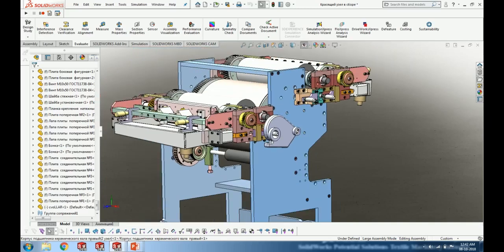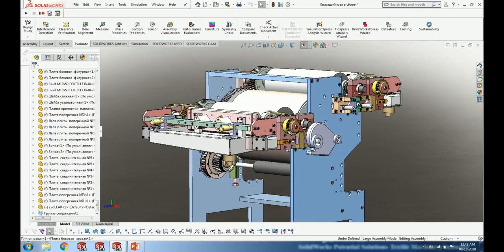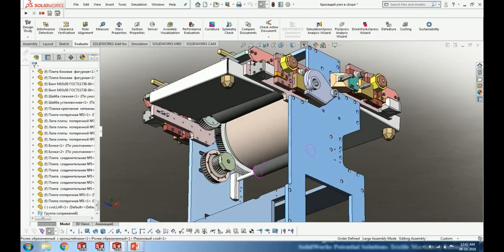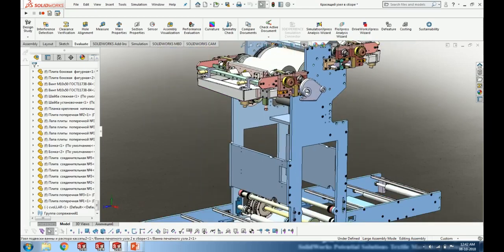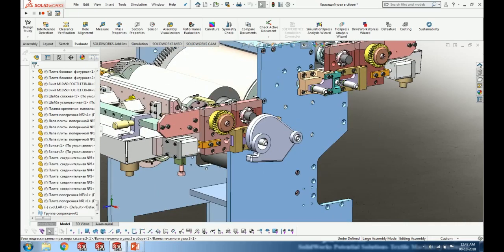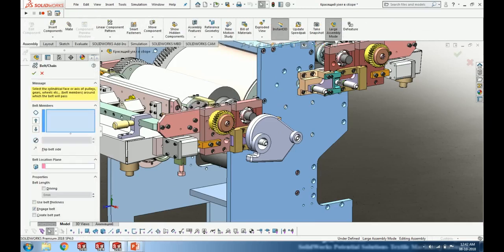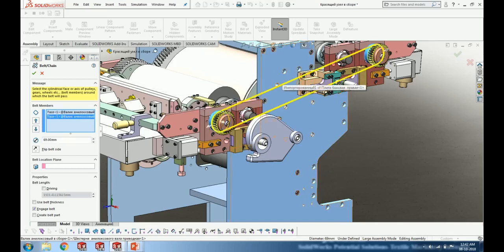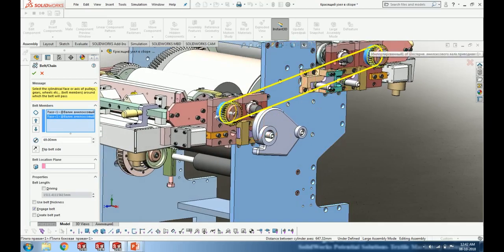Here you can find the different mechanisms like the gear and the shafts, and beneath this part you can see the different kinds of toolbox. In case we want to create any belt, we can create that instantly. Here, between the two sides, I want to create a belt, so I can go to the belt or chain creation and, choosing the two shafts, you see I can instantly create the length of the belt. And what is the exact length I need to create or purchase the belt for the mating of these two components.